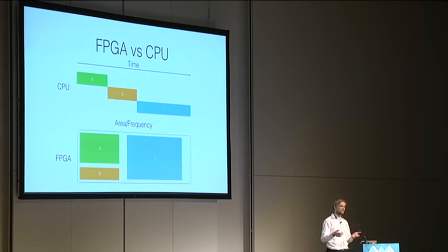Most of the time it does not, because you're constrained by some external clock, or maybe you're doing USB data transfer, or you have a camera that is clocking your data into the FPGA. So in this case, you need to split up the combinatorial logic into smaller blocks and distribute them, so that in one cycle you're doing a part of the addition, and in the next cycle you're doing the next part of the addition. And so that you can increase your frequency.